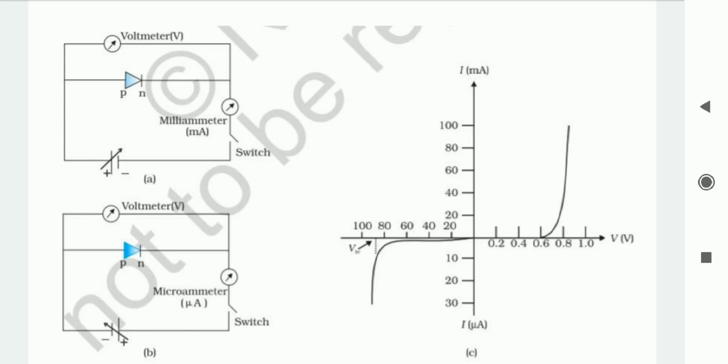Here the generated forward bias voltage is available across the diode. Silicon has a cut-in voltage around 0.7 volt. Up to 0.7 volt, the generated current is very low, in terms of microampere. After 0.7, the barrier potential reduces and the depletion region width diminishes, which increases the current exponentially.